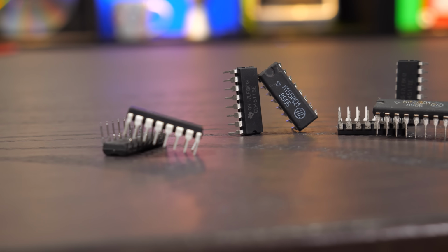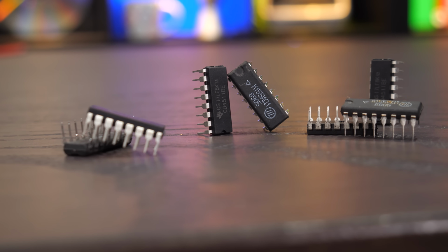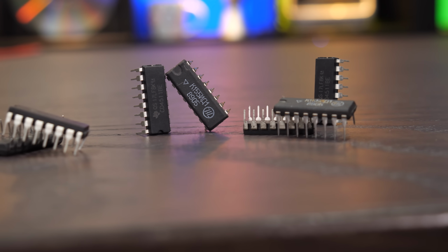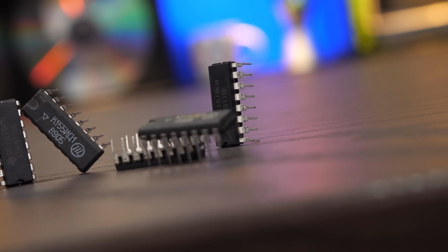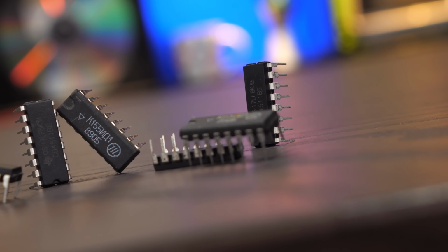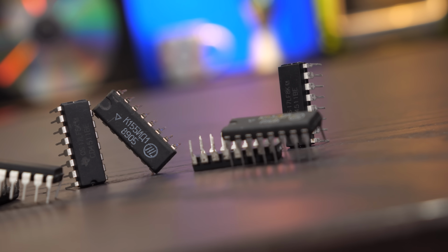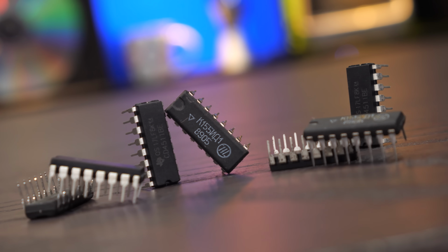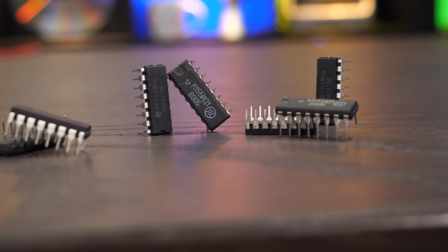In the early days, dedicated ICs, known as BCD decoders, would translate the 4 bits of binary-coded decimal input they received from a microprocessor into the correct output to drive a display device. The internal structure of these decoder chips was quite simple, just a few logic gates really, but they could be a lot simpler with a 7-segment display compared with a Nixie tube, since there were fewer outputs for it to control. And many of the same outputs are active on multiple inputs. A 2 becomes a 3 simply by swapping these two segments, and that reduces the number of transistors you need in the chip, which makes the chip cheaper. That's extremely in the weeds, though.